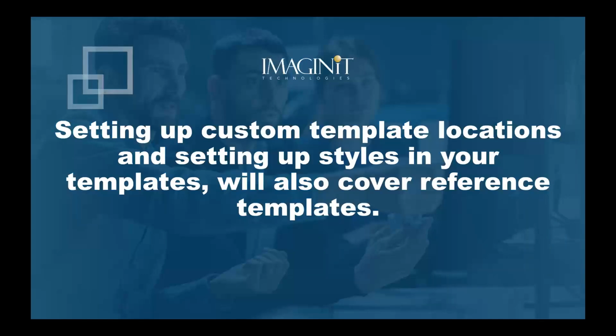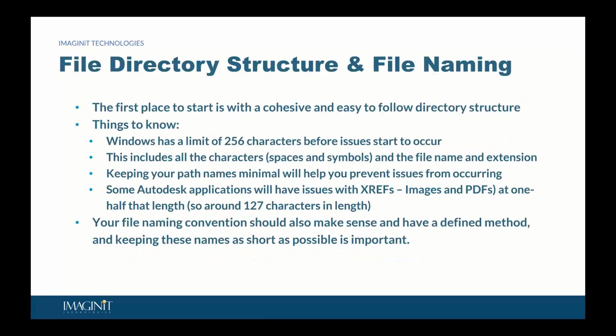Shortcuts seem to be an issue at times when path links and lose links. Yes, absolutely. This comes all the way back to that 256 character limit. So if your shortcut folder is buried deep and you go look inside that shortcuts folder, you'll see that long hexadecimal name XML file that relates to that. Sometimes data shortcuts will not reload correctly because it simply can't parse that amount of data.